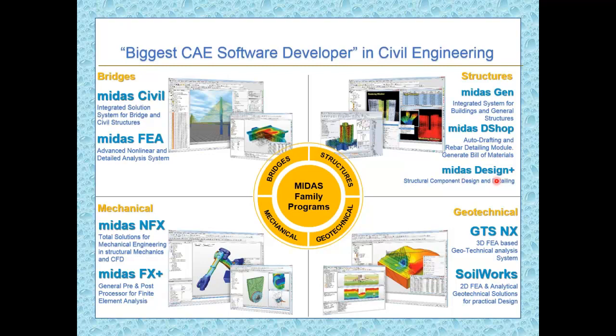Then there is Midas Design Plus. In Midas Design Plus, as per Indian standard, we can have footing design, RC footing design, and pile cap design done. And we can get the drawings done as well. A good part is that Midas Gen analysis can be directly imported in Midas Design Plus for that particular footing. And then we can simply go ahead and click on Auto Design and get the drawings generated along with the bill of materials. So basically, these structural solutions are completely integrated with each other.